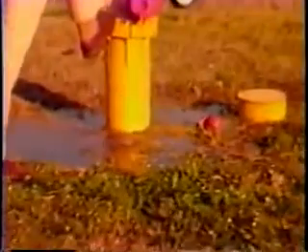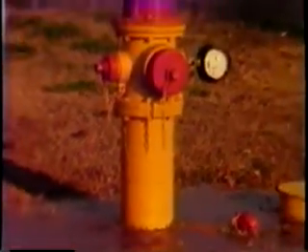To get an accurate reading of the pressure at the residual hydrant, it's only necessary to open the hydrant a crack, but you shouldn't do this because there are drain holes in the bottom of the hydrant that remain open until the hydrant is wide open. So if you only open the hydrant a crack to read the pressure at the residual hydrant, you'll be causing water to flow through the bleed holes and undermine the hydrants, as you see here.